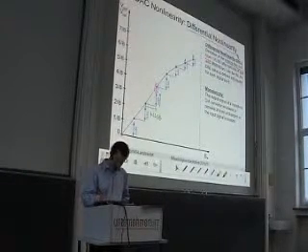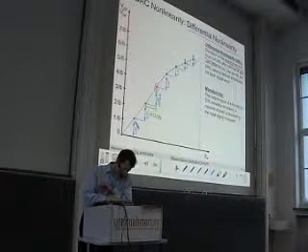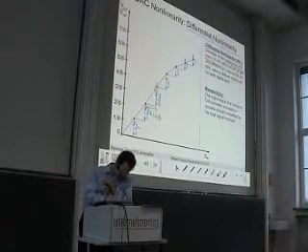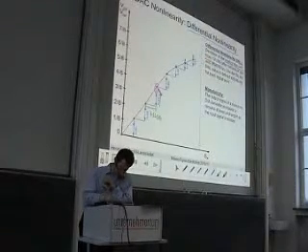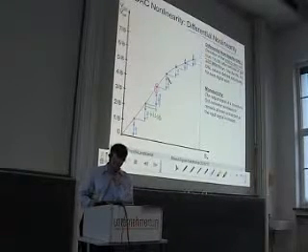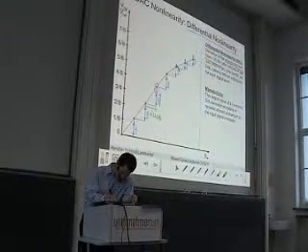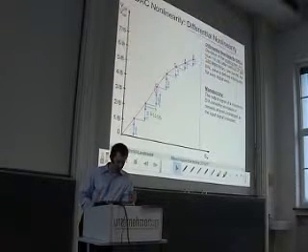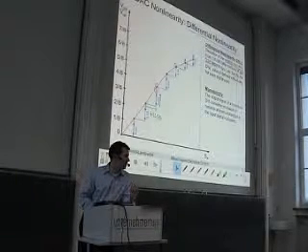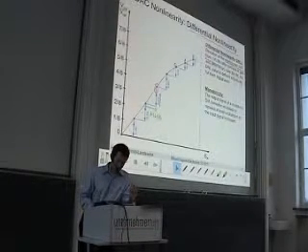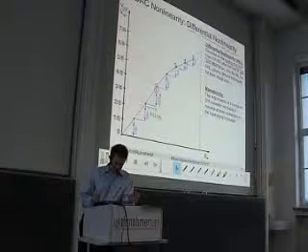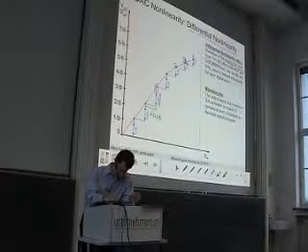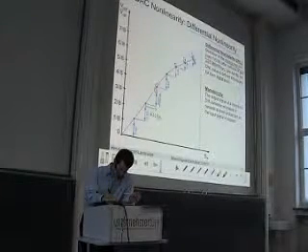So you can see here the step is slightly larger than it should be, so we have positive differential nonlinearity. Here the same, here of course the same, here also the step is larger than expected. Then at the next point you see the step is smaller than expected, so we have a negative differential nonlinearity. The same holds for the next two steps, they are smaller than they should be, so here we have a negative differential nonlinearity.